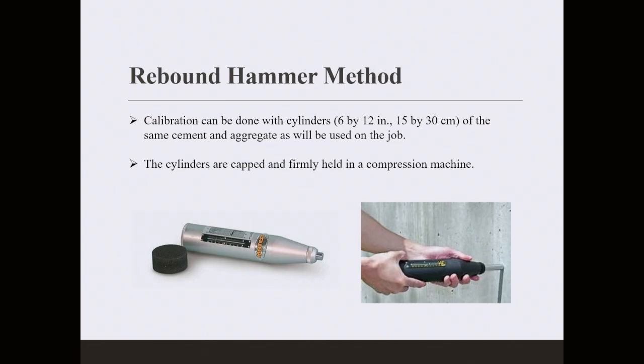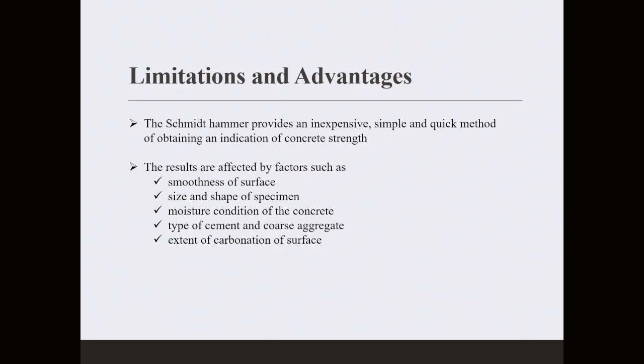It's always like that. So you have to consider exactly: are you doing a horizontal test for a wall, or are you doing down for a bridge deck or a roadway, or doing up for a ceiling or a concrete roof? This is about the Schmidt hammer. Now, there are lots of limitations. You have to do multiple tests because of the impact of any anomalies, any air pockets, any voids, any coarse limestone particles, or any steel rebars right below the surface you are inspecting.